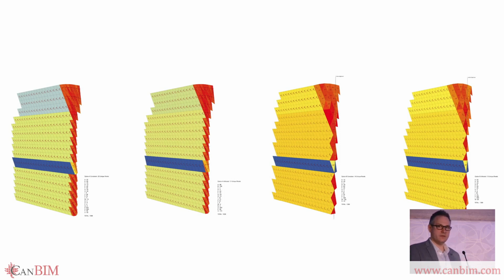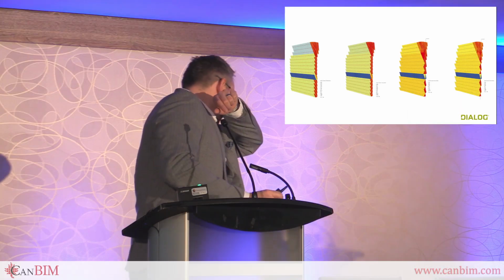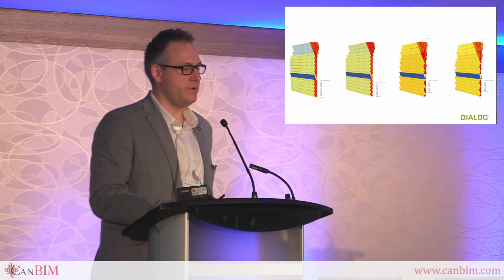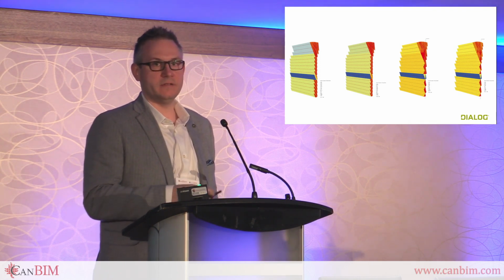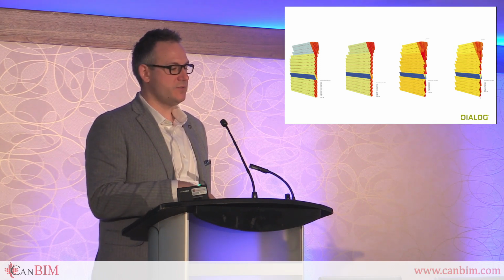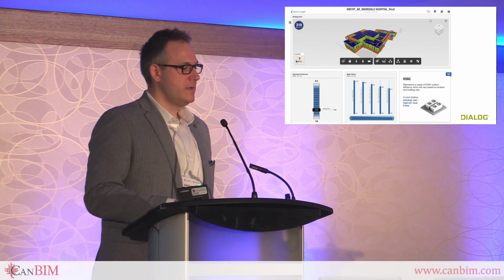You'll see that the blue lines around the middle are essentially a transfer zone where we go from one element of the tower to the other. They're a little bit different because they absorb the transition based on the twisting of the skin. And the corners essentially are all unique. What's interesting is that we brought in a third-party consultant to evaluate our findings to see if we were actually on target in terms of meeting our construction tolerances as well as our optimization. And we were within around 0.7% of a third party evaluating our optimized design. So we were really proud of that.